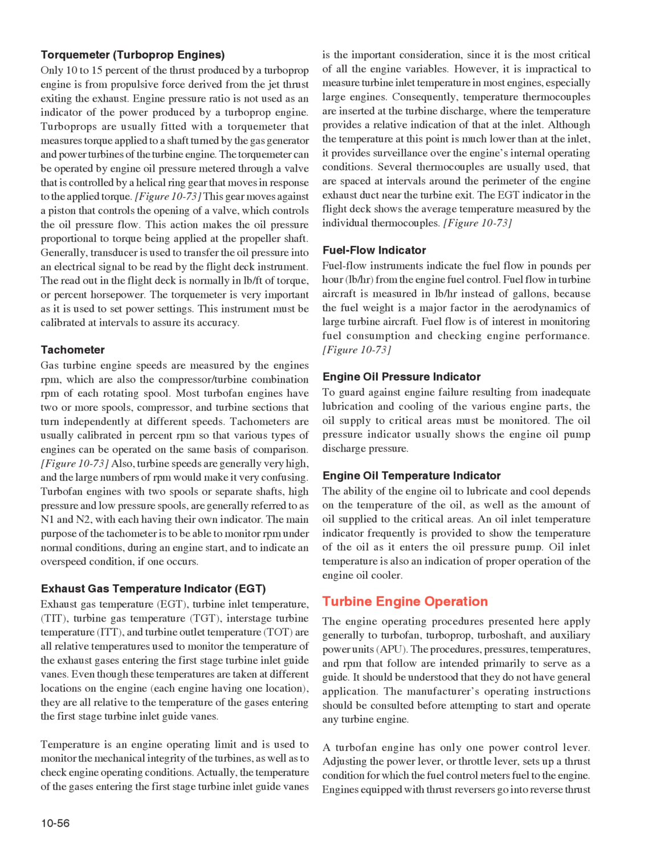Even though these temperatures are taken at different locations on the engine, each engine having one location, they are all relative to the temperature of the gases entering the first stage turbine inlet guide vanes. Temperature is an engine operating limit and is used to monitor the mechanical integrity of the turbines, as well as to check engine operating conditions.